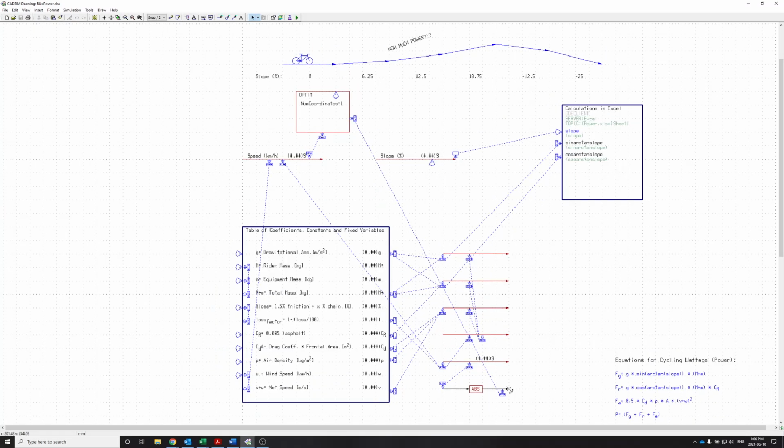Anyway, this was nice, but it wasn't very efficient, because when you're trying to get to a target set point, you would normally use a controller which has integral action that continues to try and narrow the gap to the set point.